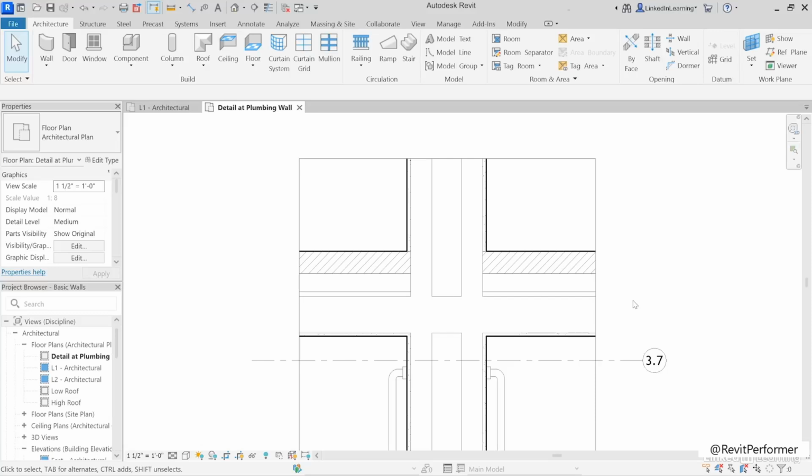The metal stud layers in both walls are intersecting each other and cleaning up seamlessly. And that's because both the priority, structure, priority 1, and the material, metal stud layer, match. If either of those don't match, you'll get some sort of a seam there. It won't be smooth and continuous.